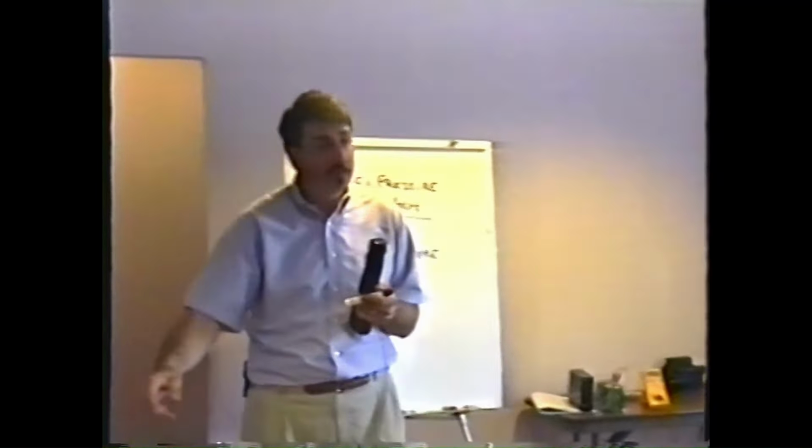Instead of trying to do this in your head, look at it and say to yourself, okay, brown is 1, black is 0, yellow is 4. 4 zeros, 1, 2, 3, 4, and then put the comma in and see what the hell you have. Because it's very easy to drop a 0 or add 1 accidentally, especially when you get into something with a large number of zeros. So don't agonize over it. Just write it down. Just write down whatever it happens to be.